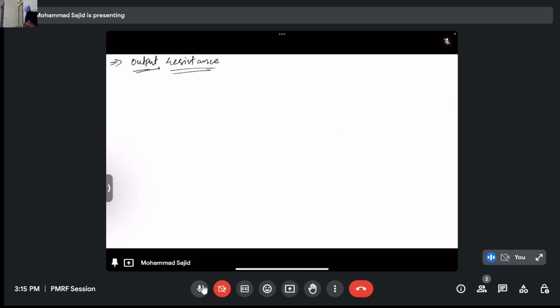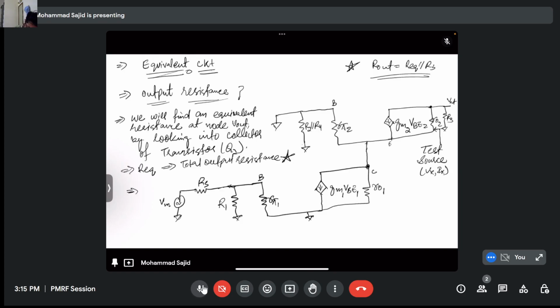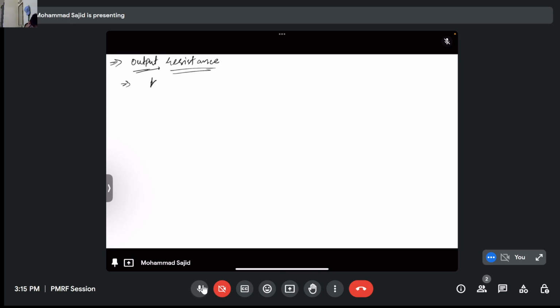Okay, so let's start from this node. We attach Vx to it, and let's call this terminal V1. Okay, so let's start a nodal analysis. KCL at this node. We have attached Vx to it, so it will be at a potential of Vx, right?